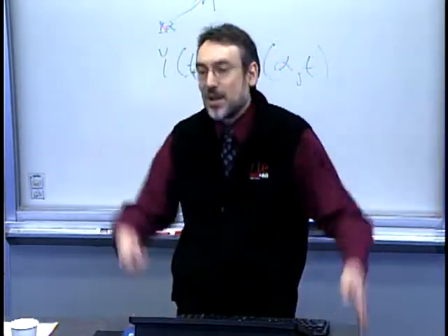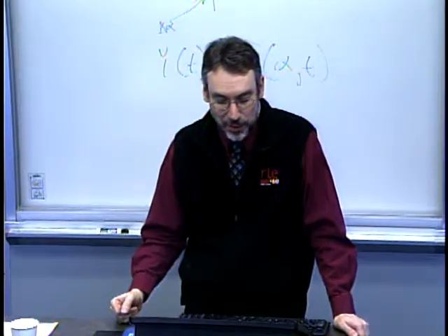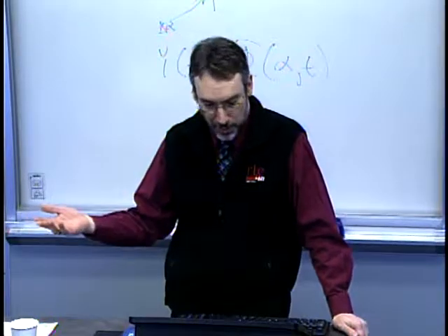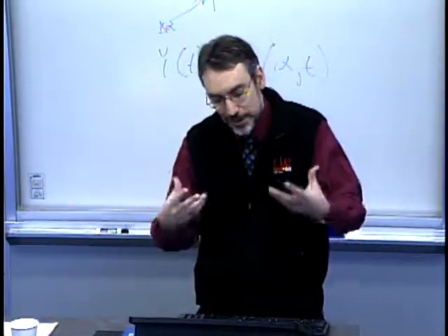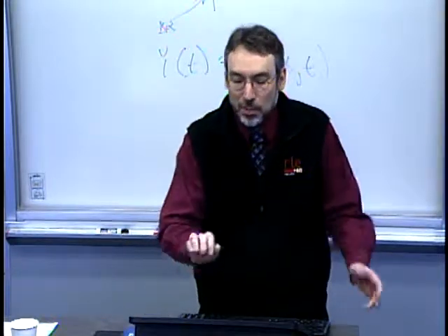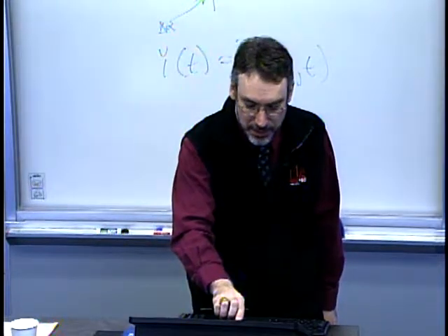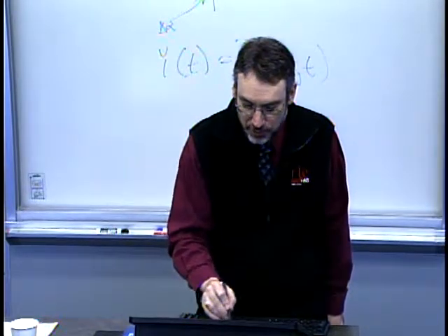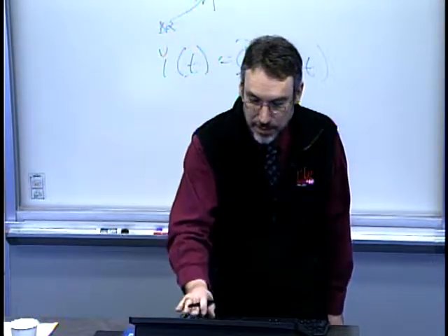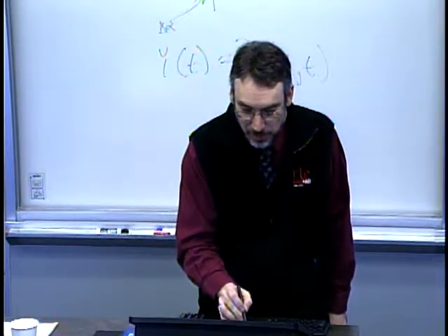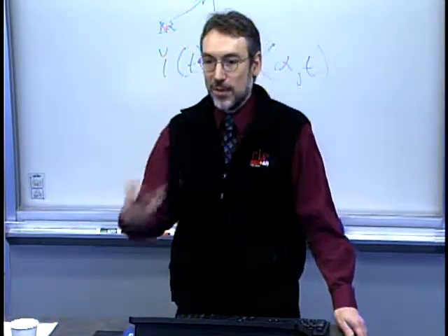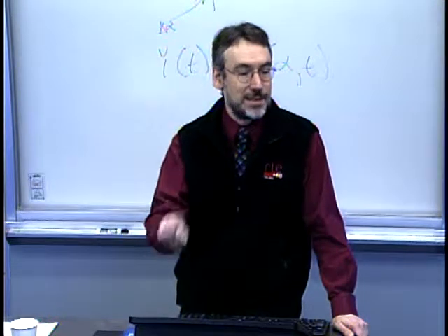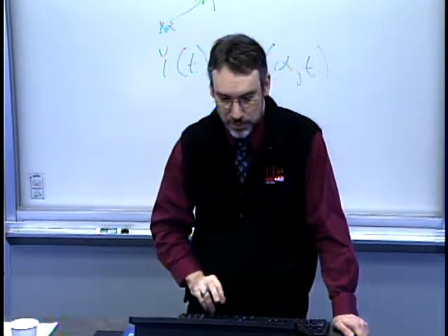Very interesting. So a couple of the points here, the kinds of things that we might be looking for are deterministic and systematic kinds of effects that we might want to use modeling for. And then we also are starting to get close to the statistical process control thinking, which is to say we would like to know the inherent or natural variation of the process, have to do with these sorts of bands, and then be able to detect with high degrees of confidence that something strange has happened and I better take action. And that's SPC, or statistical process control.